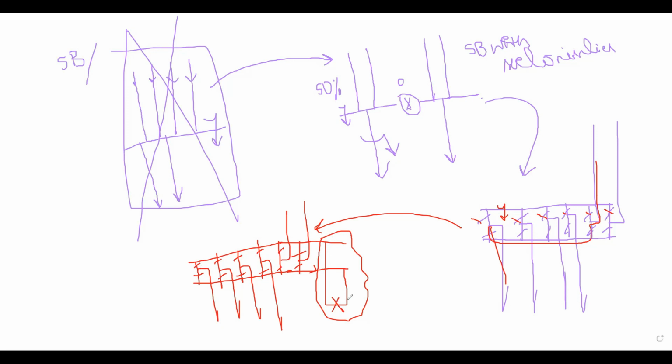Here, with the help of this bus coupler, I will close the bus coupler. So the potential will be transferred to this bus. Now this bus has 220 kV or 33 kV potential, and this incoming node has the same potential. If both potentials are the same, you can close the isolator and open the other isolator. So without interruption, you can transfer the power from one bus to the other. This scheme we call the double bus with the bus coupler scheme.